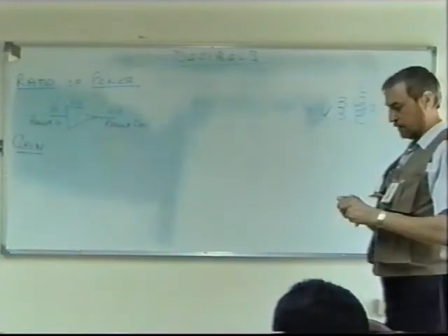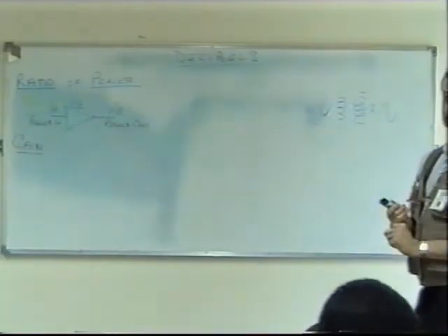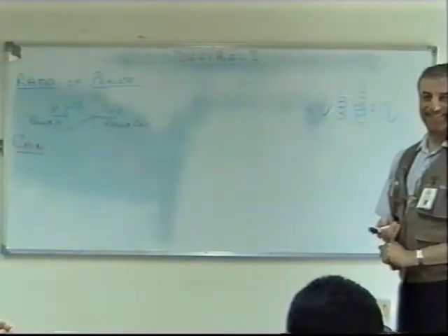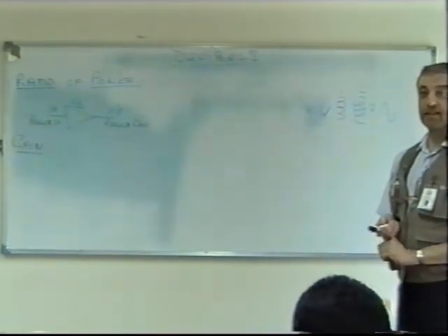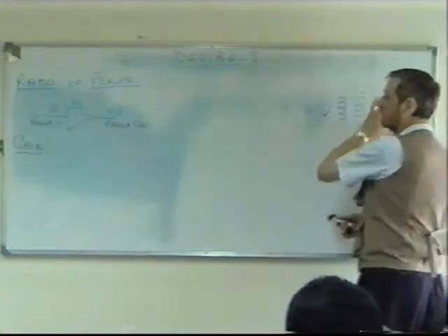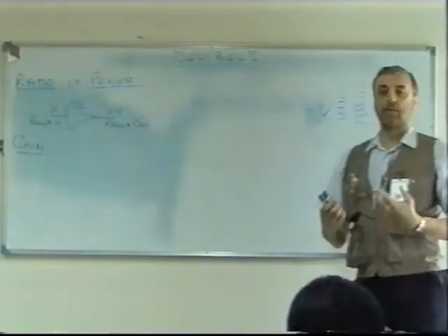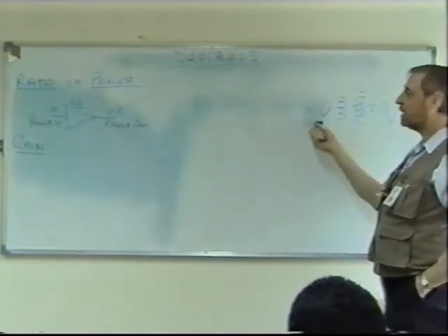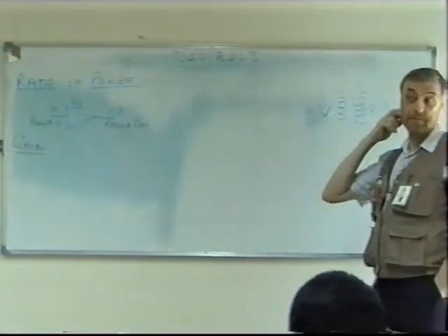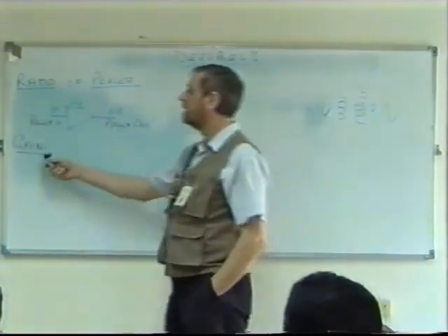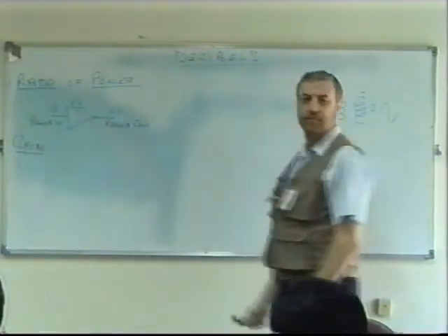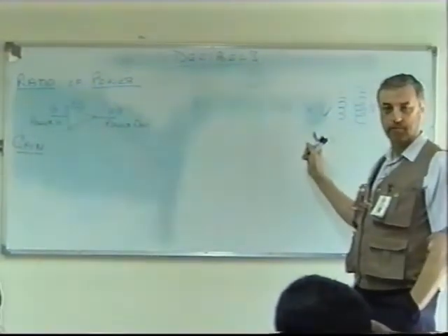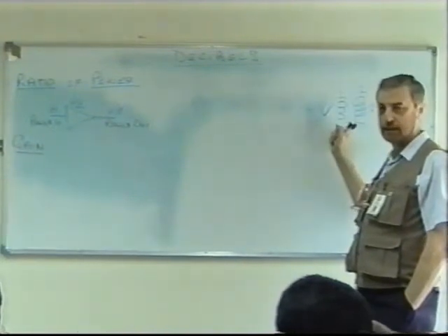Okay. Now, the first question is, what is the gain of this transformer? 2. We don't use it as a gain. Right, so what is the gain? 1 to 2. What has this signal gained? Nothing. Gain actually means you must get something, something has got to be added to the signal. Nothing's been added. All we've done is change the ratio of voltage to current, really, haven't we? We haven't added any power. When we talk about gain, we've got to speak about power. So in a transformer, the power output is equal to the power input, isn't it? So there is no gain in a transformer.